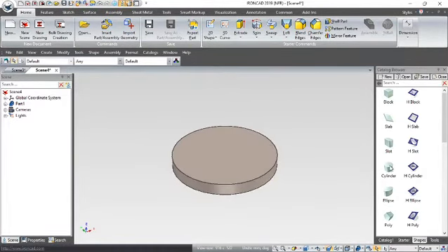What I can also do is drag another cylinder in, and I'll put that on the top like so, just drag it over to the center point, and that'll put a block in there like that. And maybe I'll make that 150 diameter and come up here, and I'll make that, say, 25 like so.